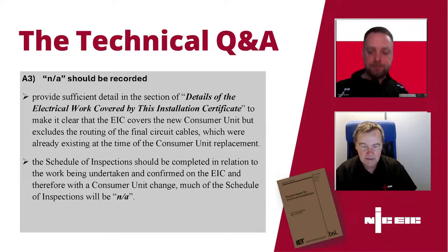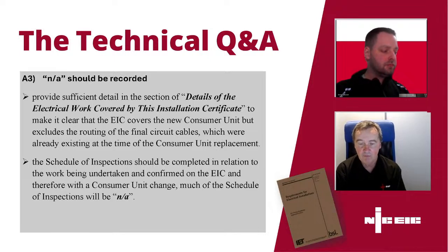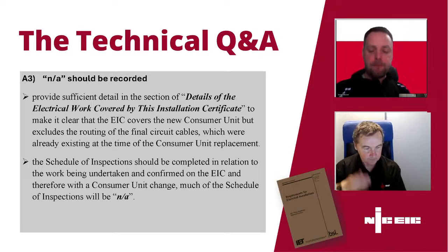And the installation certificate clearly lets you say, right, what work is covered by this certificate, and you've also got another option on that certificate where it says comments on existing installation, where you could, if you noted something that wasn't a safety issue and didn't prevent you from completing your work, then you could still record it, and by that way you're making it very clear that was there already and it wasn't something which you introduced to the installation. Would you add anything to that, George?